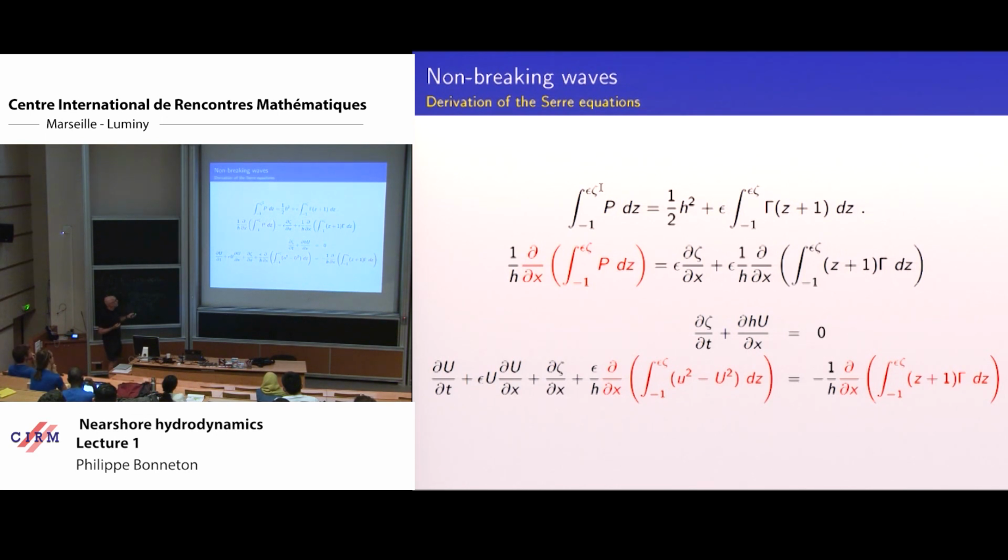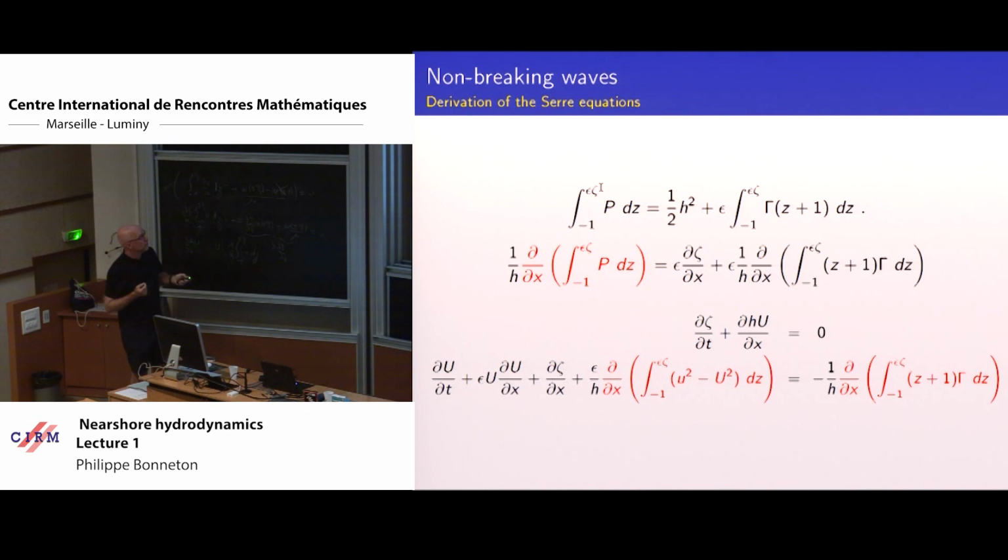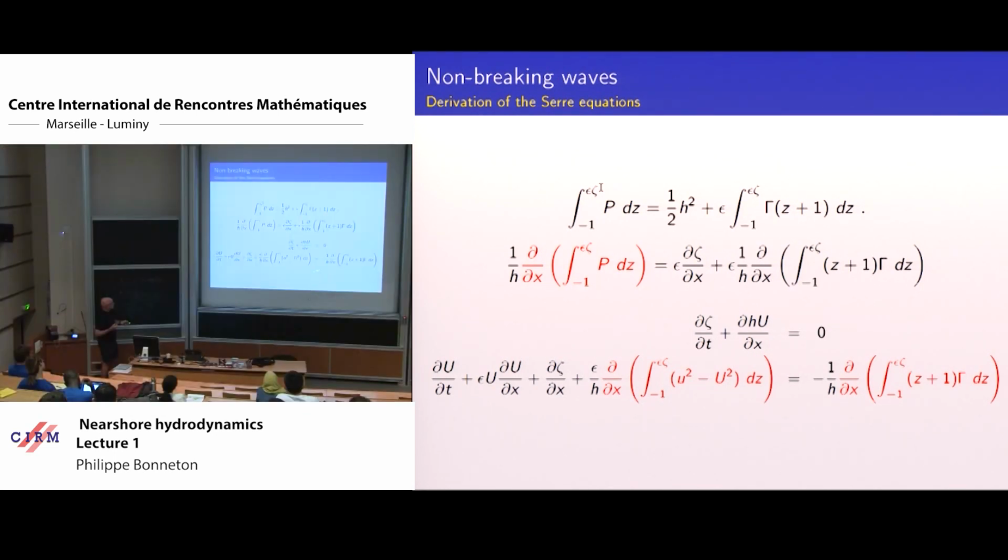So we have divided this unknown term into one known term, this one, the gradient of the hydrostatic pressure, and another unknown. So the equation system can be recast into this new form with the gradient of the hydrostatic pressure and two unknown terms. So the system is of course not closed. To close the system, we will use an asymptotic perturbation method based on the small parameter mu.